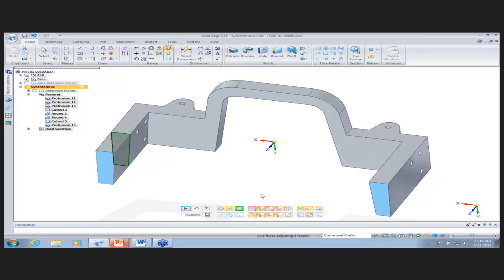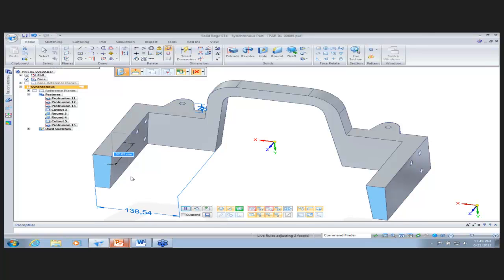The options you select are clear in the maintain list. For the current edit operation, they are saved for future edit operations in the current design session, and when you exit Solid Edge, these current live rule settings are maintained for the next design session. So if I were to close this part and open it again, symmetry would be turned off, since that's how I have it saved right now. And so if you're going along and you have certain live rules turned on or off, you can always restore them by hitting the restore button or hitting R on your keyboard, and that'll restore our symmetry there.